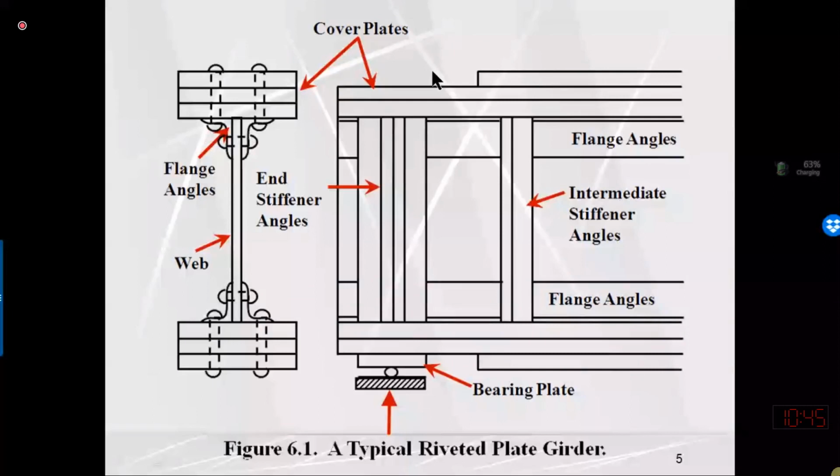So then this is the angle section that is used throughout the length. Here you can see this is protected. And then we are having this stiffener, two types of stiffener. One is intermediate. This is also used as an angle section. So this is the projected leg, and the other leg, the flat leg, is used to connect the angle with the rivet or fastener with the web.